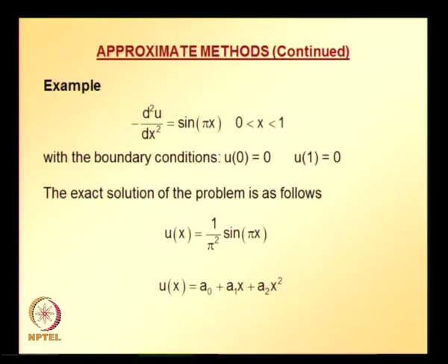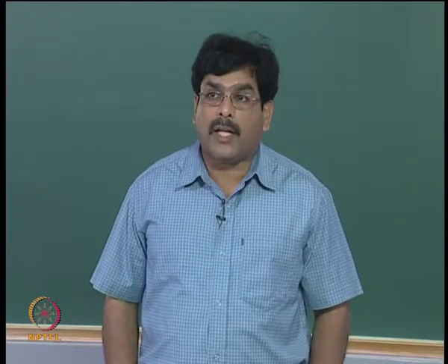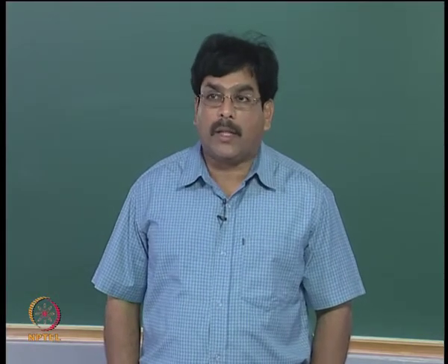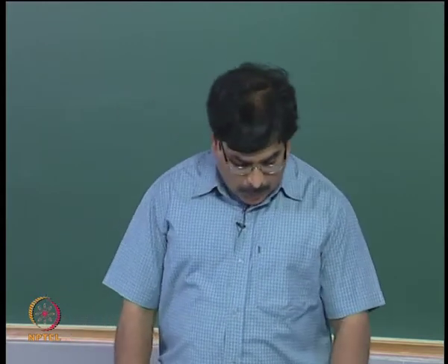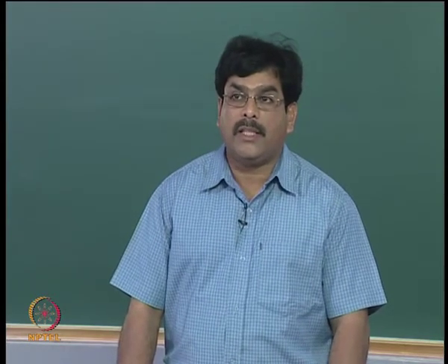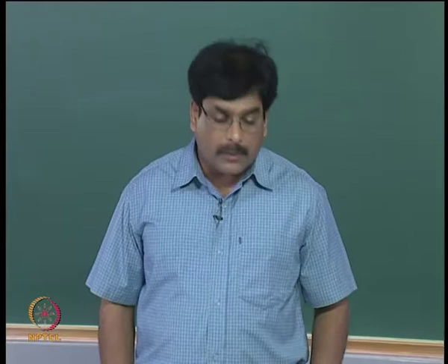and before we substitute this trial solution into the residual, the trial solution that we use needs to be an admissible trial solution. An admissible trial solution is a trial solution which satisfies essential boundary conditions. So, once we assume a trial solution like this, we need to make sure that it satisfies the essential boundary conditions. Before we proceed, we need to make sure that this satisfies the conditions: u evaluated at x equal to 0 is 0, and u evaluated at x equal to 1 is 0.